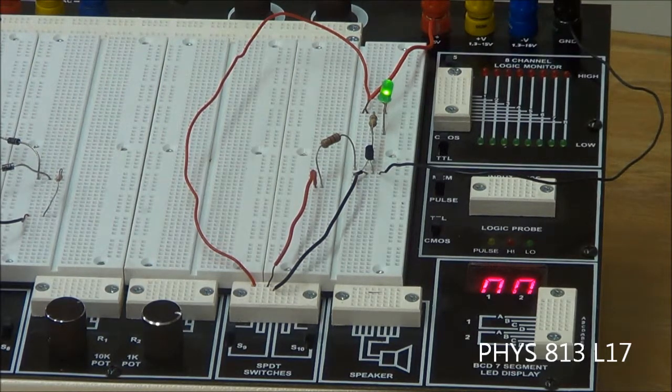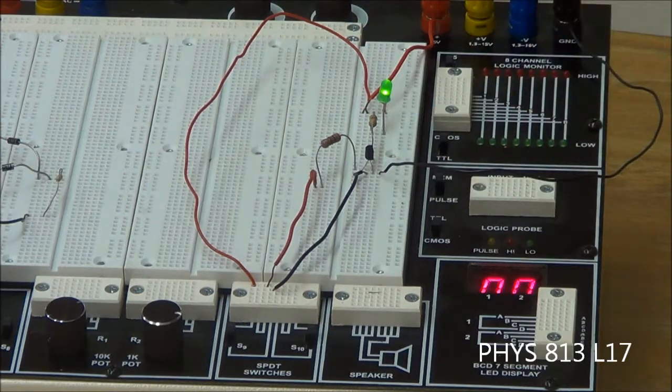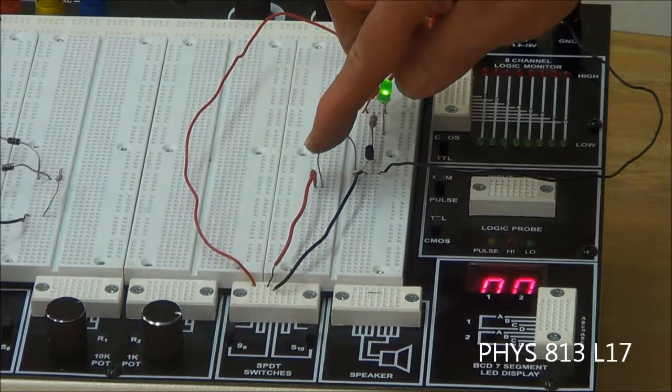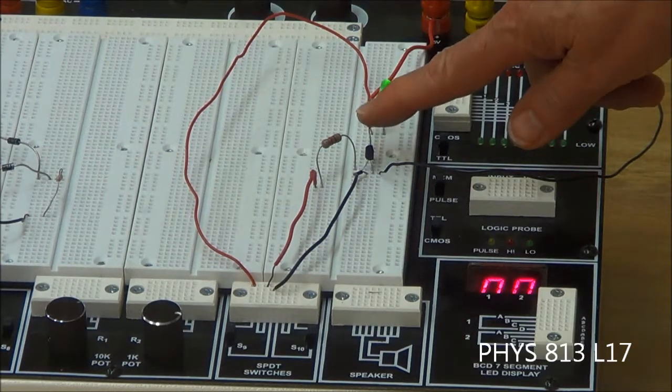Everything looks fine. And then we're going to use, I'm not going to do it because I've already done it, probably, it doesn't really matter which meter you use, the orange meter or the yellow meter, set at voltage, and you're going to measure the voltage across the LED and the voltage from the collector to the emitter, so it's these two sides of the transistor, and the voltage across RB, which is the base resistor, and the voltage across the collector resistor, which is the 100 ohm here.